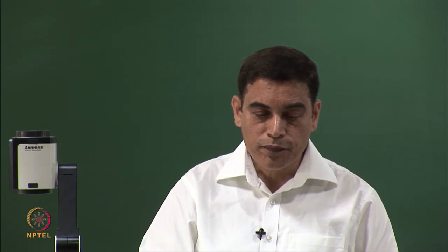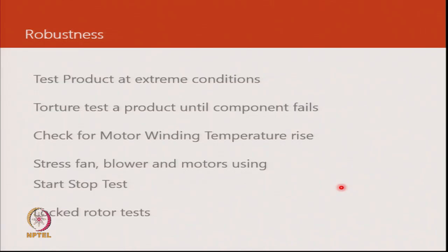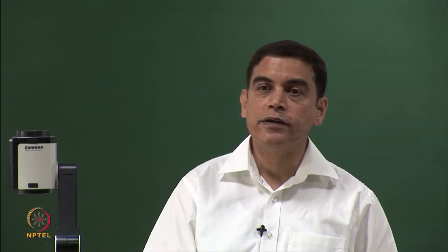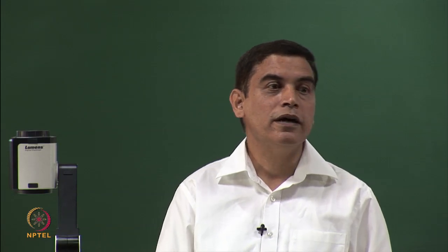Similarly, the plastic components or metal components for fan and blower can be put to stress tests or torture tests. So, you put them to very frequent start, stop, and then check for critical areas where cracks may develop. And sometimes you test them long enough that they actually fail and then reinforce them, because the process of making tools, molds, etc. allows you certain quick corrections at the design stage.